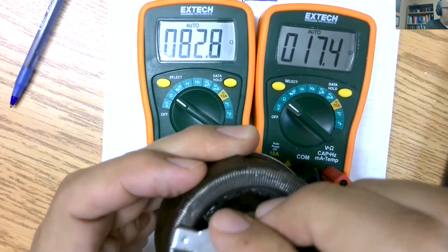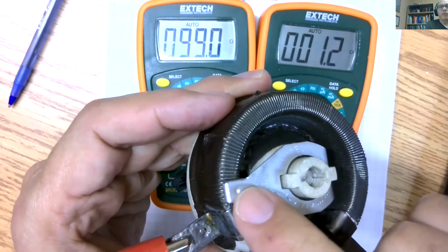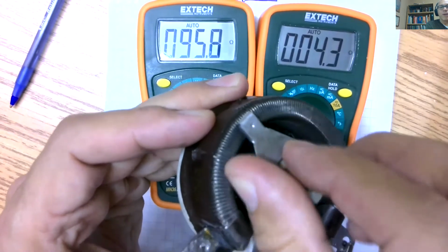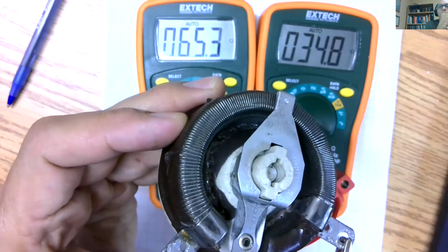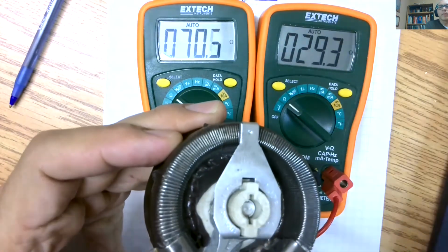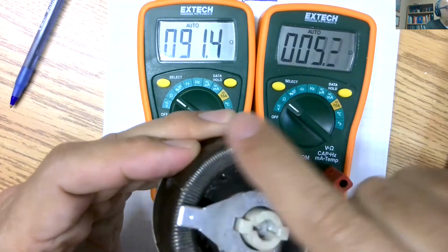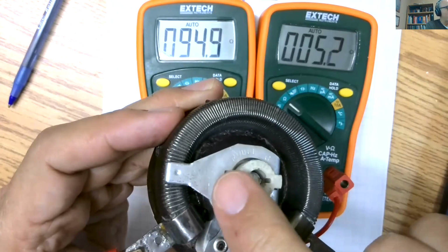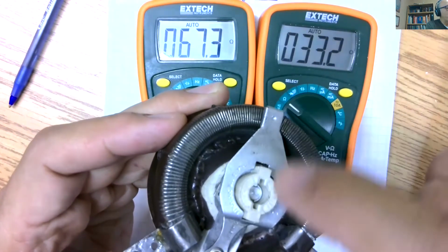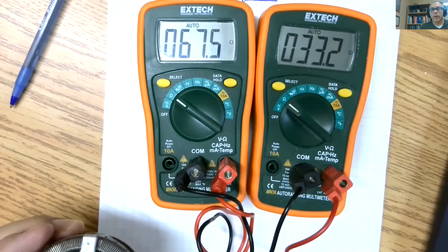So this will keep changing. And as we move closer to the one pin, the resistance between here is very small, which we see at 1.2 ohms. And the resistance going all the way around to the other pin is very large. If I go halfway, or what I think is halfway, then we'll start to almost even out a bit. Oh, I'm close to halfway. So we'll just keep moving those. And that's how a variable resistor works. You have a constant resistance from pins 1 to 3, and you have a wiper that moves along it. There's always a resistive element and a wiper that is connected to pin 2. This is my favorite variable resistor for demonstration purposes.